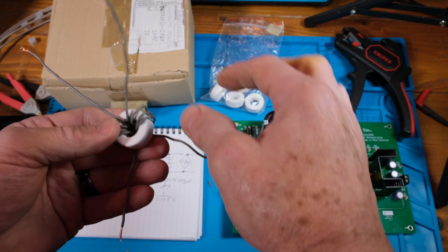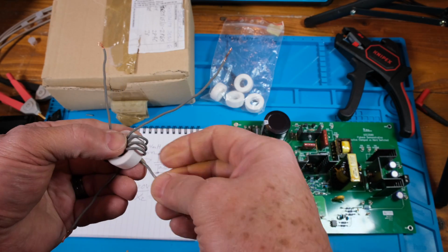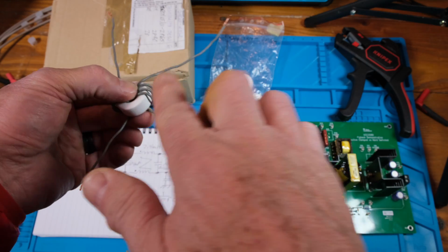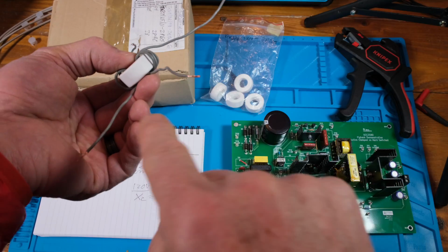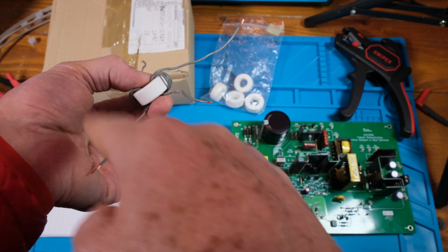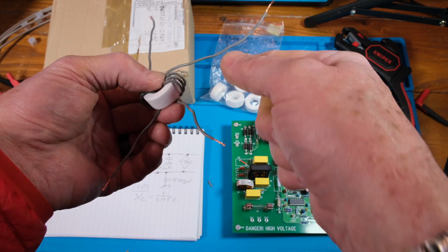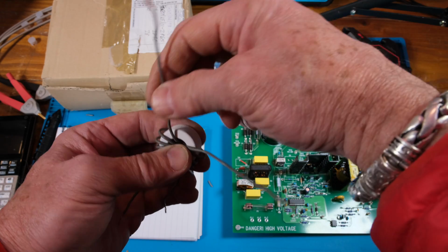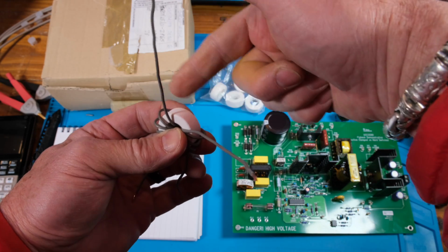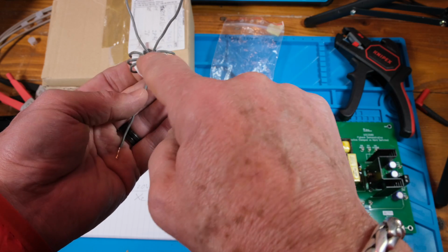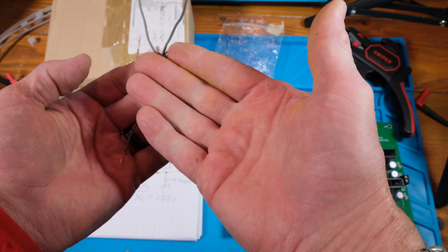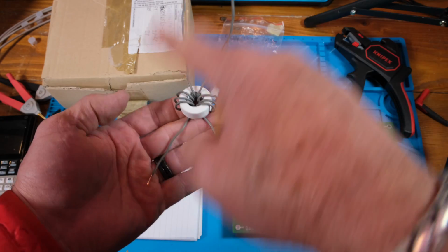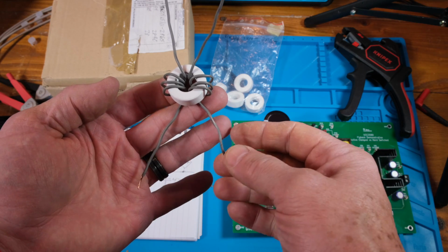Alright, so let's just see how the current flows through this thing, okay? See if we did it right. So as the current comes in here, let's say the line current's coming in here, running through the circuit and coming back this way. As it comes in, it's going clockwise around the core. It comes out, goes out to our circuit, comes back, hits this one, and now look, it's going counterclockwise. So clockwise here, counterclockwise there, the fields cancel. So differential current that circulates through our circuit cancels. And that's what we want.